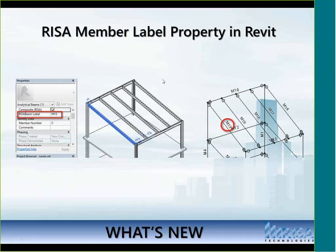We've introduced a member label property in Revit. So now all of your analytical beams in Revit have this RISA beam label, or your analytical columns have a RISA column label property. And that tells you what the member label was in RISA 3D. This is really handy because when you're in Revit, you can pick out a member and find out what it was named in the RISA model and easily find that same one in the RISA model. For big models where it's hard to keep track of where all your beams and columns are, that's a huge plus.